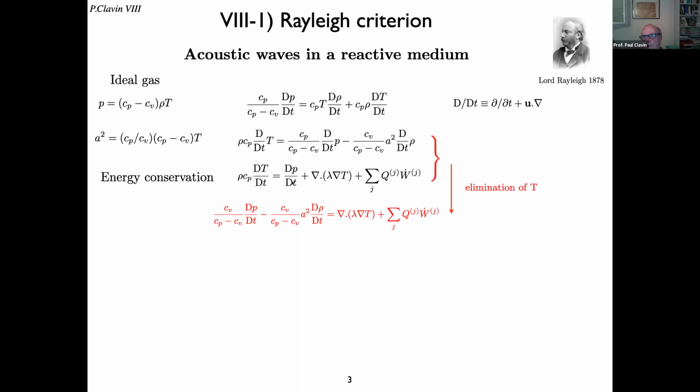This pressure term was suppressed when we were considering quasi-isobaric propagation. But here, because we want to discuss the interaction with acoustics, it's out of the question not to consider this term.